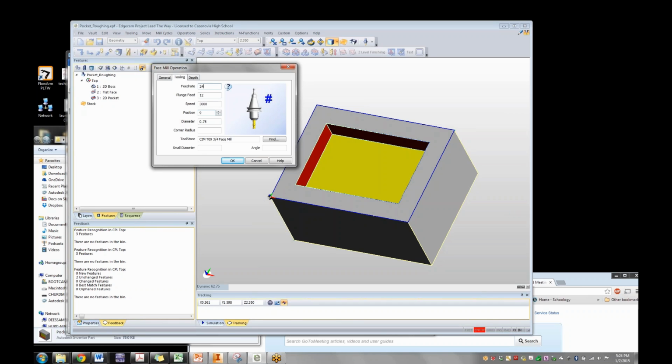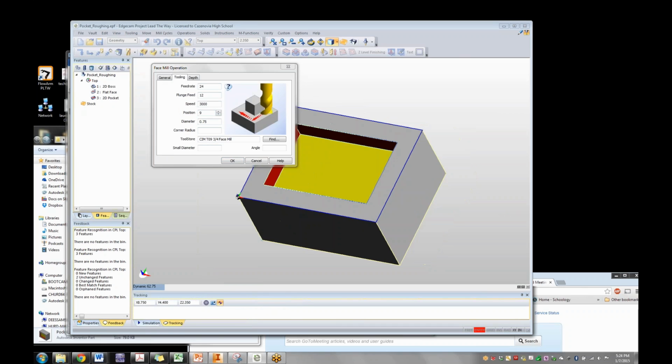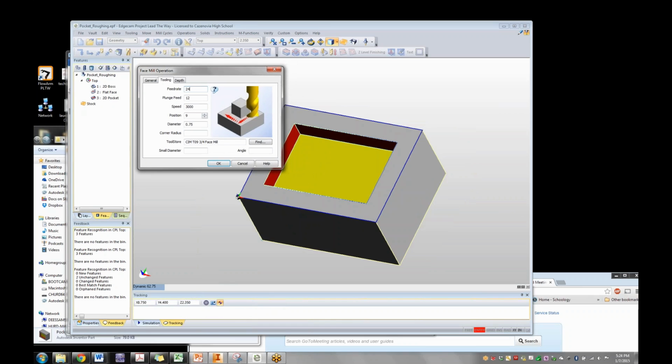If we had them calculate it for wrench shape, that would be a feed rate of something like 75 inches per minute at a spindle speed of 60,000 RPMs, which our machines can't even do. So those are just safe numbers for you that are actually running a little bit slower than they really need to, just for reaction time, to keep the machine life of your tools, your machine. But the kids don't necessarily have to worry about those numbers. Now, if you're finding that those numbers, if you have a LabVolt or a Denford, are a little bit too fast for you, you can start slowing some of those numbers down. Good point, Jim. Good point.